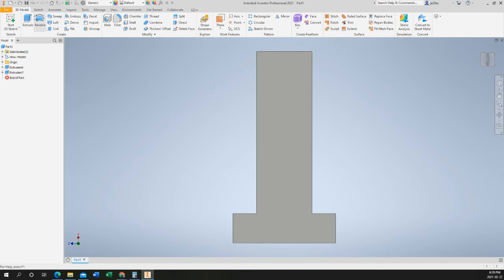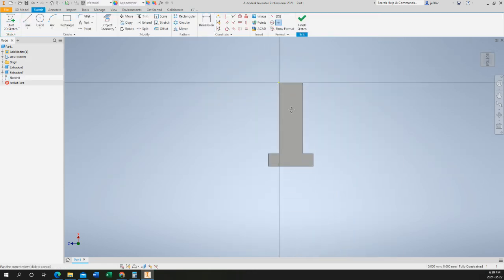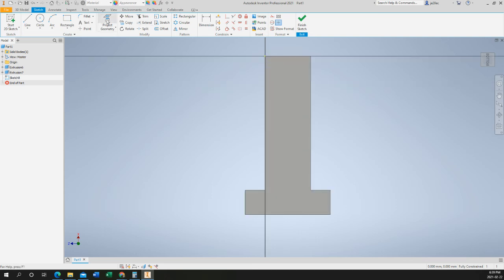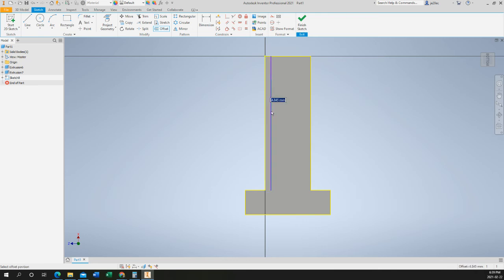And this time we will create a sketch on the face. That's similar to what we did before, but we're going to use offsets. So I can click this button, which is Project Geometry. I can select the face, the geometry I want, and you can see this yellow line showed up with all the edges of that face. I can start using these edges as reference points now. So I'll make an offset of 10 millimeters off the sides. I've clicked the edge I want to use and I pressed enter on my keyboard. And I will enter the value of 10. Now repeat that.